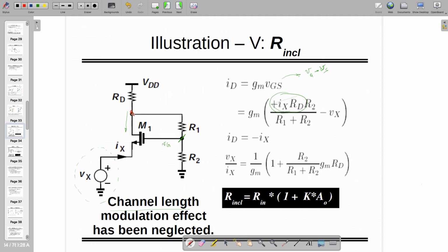Right? So Ix is the known current. The same current is going to flow through this part and this part, both. And we have to make sure that R1 and R2 values are so big that current will not flow from here. R1 and R2 are very big, so no current is flowing from this branch. And of course, at the input side, there is no current because the input impedance is infinite. This side is also infinite, so no current is flowing here or here, because it's a relatively very large number. However, RD and other things are smaller, so current will pass through them. So RD has to be much lower than R1 and R2, or you can say that compared to RD, R1 and R2 have to be very large, so that no current flows through R1 and R2.